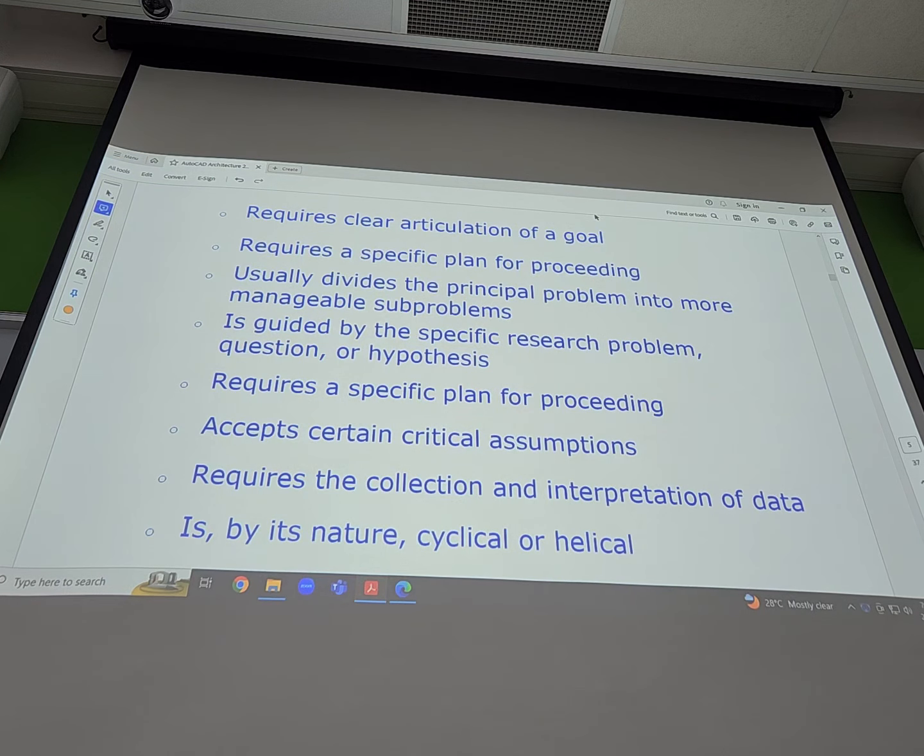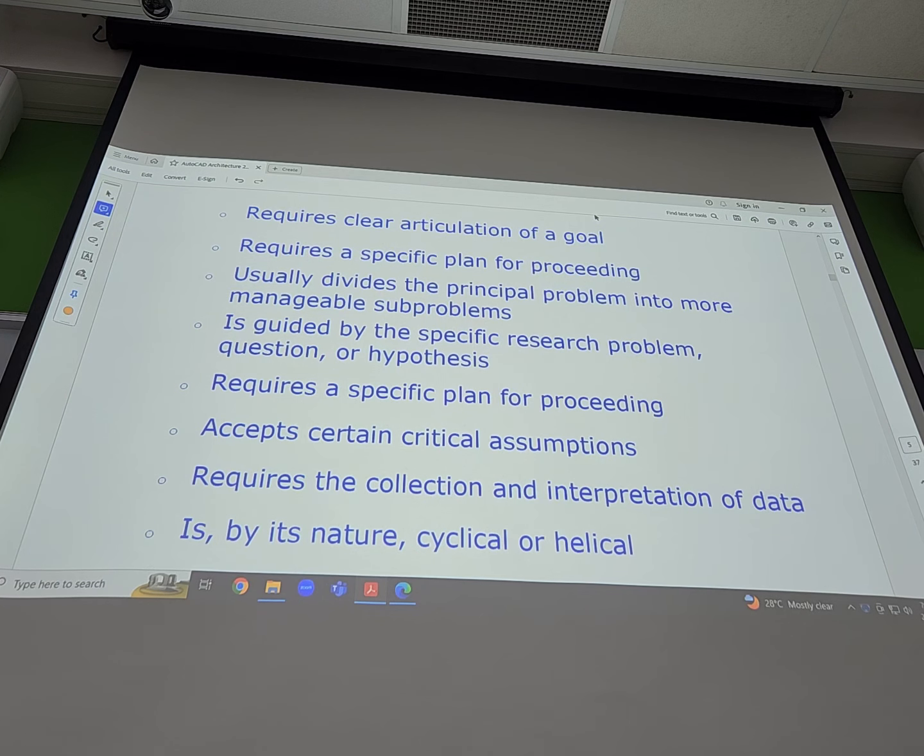The primary data is where you are going to record for yourself. So you want to stand outside and see how many vehicles pass through this particular junction every 5 minutes between 5 p.m. and 6 p.m. So what you do is just go there and record yourself. Primary data means you are doing your experimentation, you are going to collect the data, the numbers.